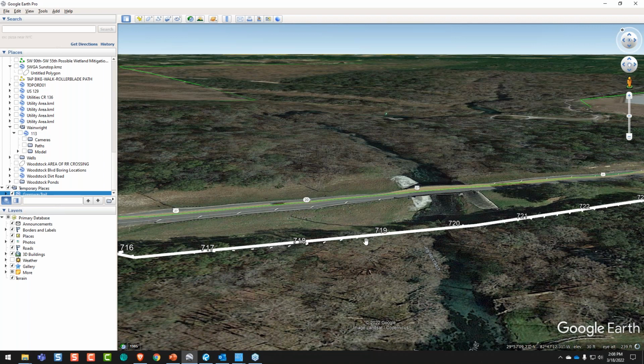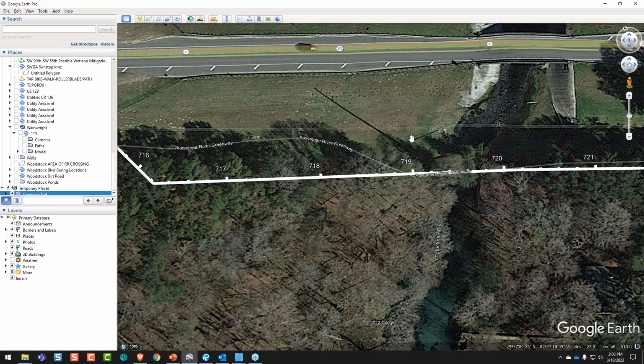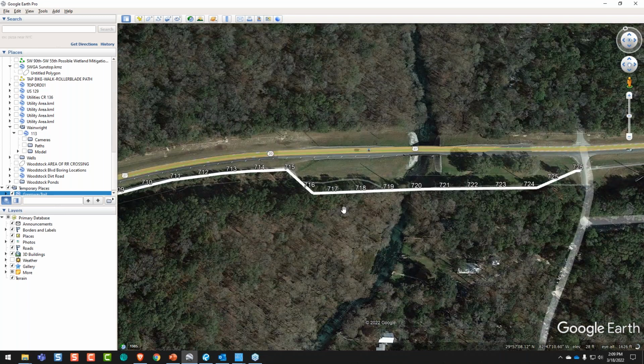Now it's got to follow DOT standards, where you have no spacing larger than 4 inches across. Obviously, they don't want somebody jumping off it, and it is going to require a canopy as well. You can't just do the flat bridge. They don't want people climbing over it, that kind of stuff. So basically, again, railroad project. It's all in this location here, and that's how this kind of came to be.